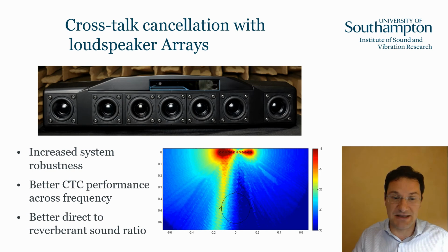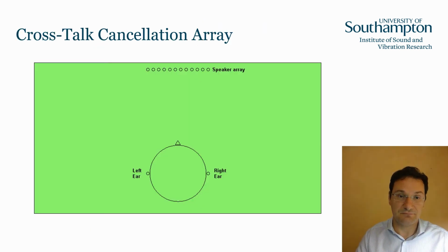And we have better performance for crosstalk cancellation across frequency. And also when we use the system in a reverberant environment, because the beamforming approach creates such a tight beam of sound, depending of course on the number of loudspeakers we're using and on the frequency, but in general we can achieve a better direct to reverberant ratio and therefore ultimately better crosstalk cancellation performance. So one could say the more the merrier.